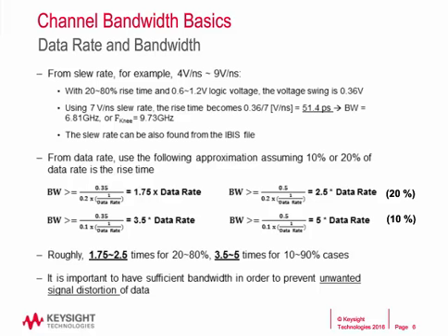A high-speed channel is every interconnect between the TX and RX chips, which may include packages, connectors, boards, cables, vias, etc. As you know, today more bits are transmitted over the same channel due to higher speed requirements, mostly driven by advanced mobile and network applications.